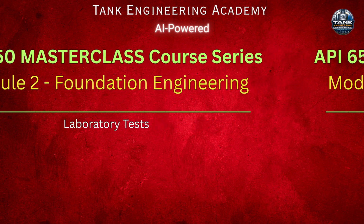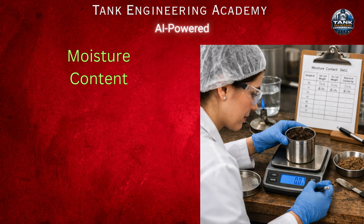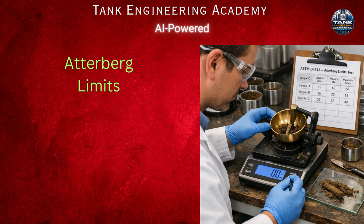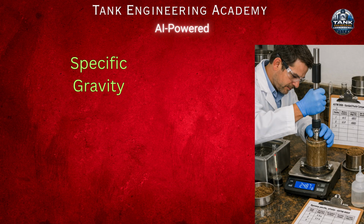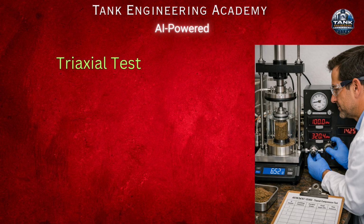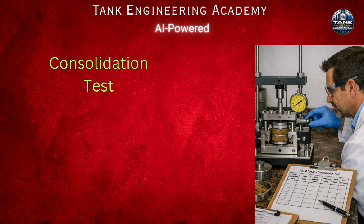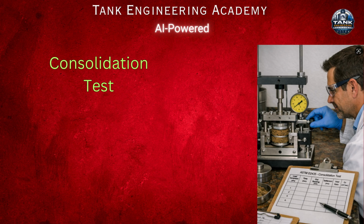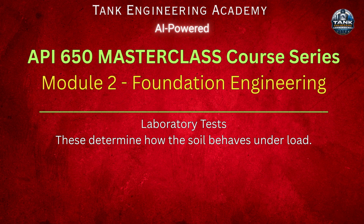Laboratory tests. After collecting samples, they are tested in laboratories. Typical laboratory tests include moisture content, Atterberg limits, grain size analysis, specific gravity, compaction test, triaxial test, direct shear test, consolidation test, chemical analysis. These determine how the soil behaves under load.